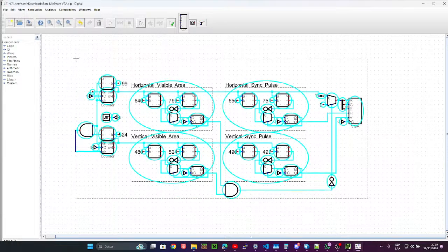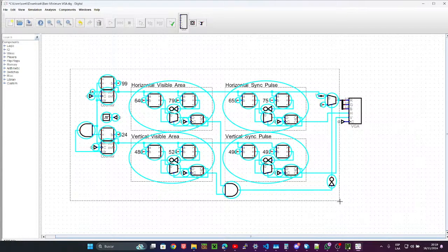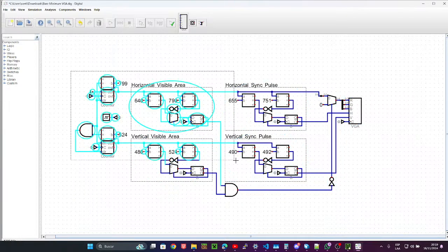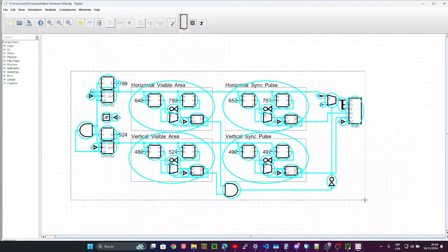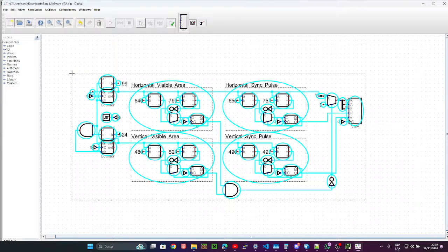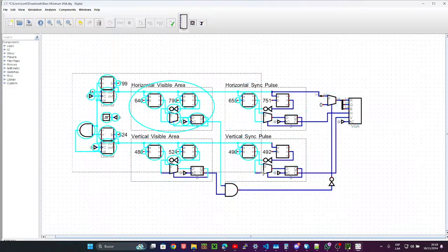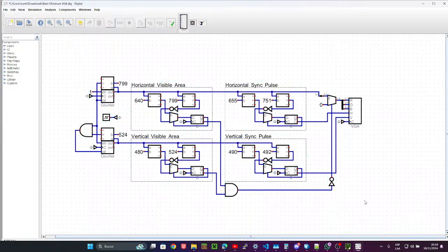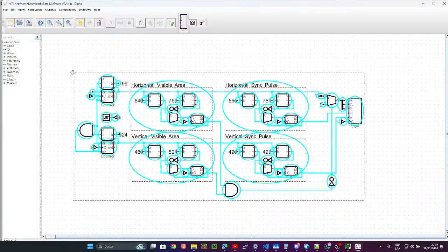So if you want to reduce memory consumption, you introduce layers of abstraction. So you remember the thing I said, by downsampling the VGA by 16 on both axes, you get 40 by 30. Yes. Well, if you do it half as often, you get 80 by 60.